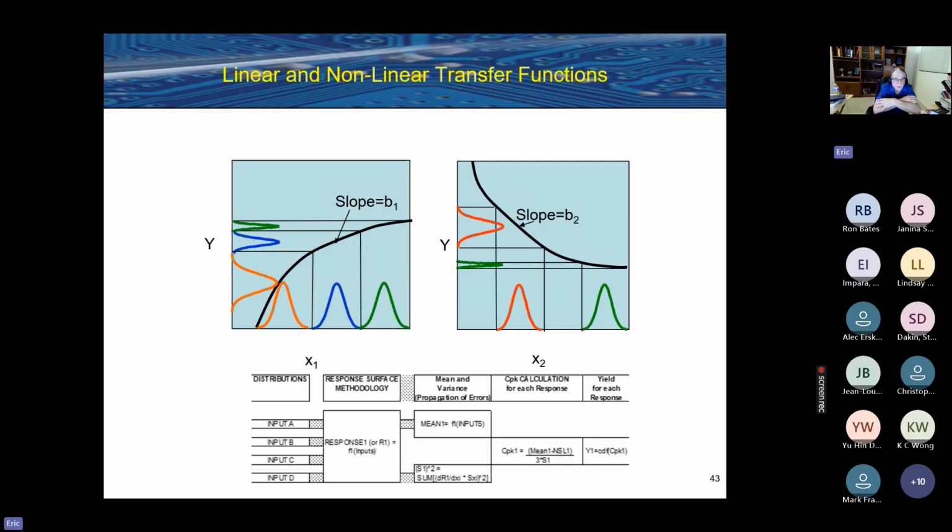So what Arshad and I did then was we took our equation from our design experiment and our RSM, predicted the mean, predicted the variance using that equation from Hahn and Shapiro's book, and combined the mean and the variance together into a CPK and a yield. Assuming a normal distribution, we can take the CPK and predict a yield from it. Basically, the CPK is the z-score divided by 3. So taking your z-score and turning it into a predicted yield.